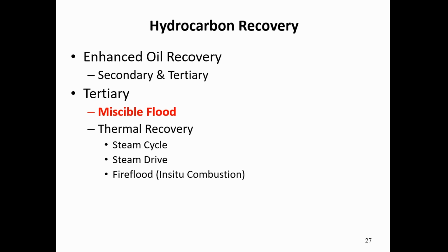Capital M, M, P for Peter, P for ping pong, and that's minimum miscibility pressure. If you make injection pressure more than MMP, you can achieve miscibility. And then what's the advantage? What's the advantage of that? The advantage of that, it will give me better sweeping efficiency.